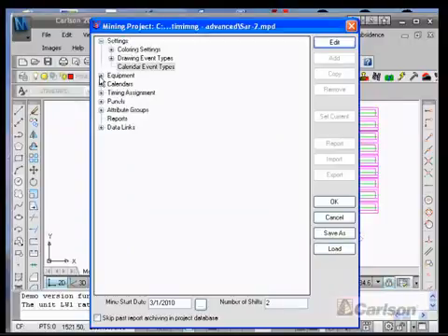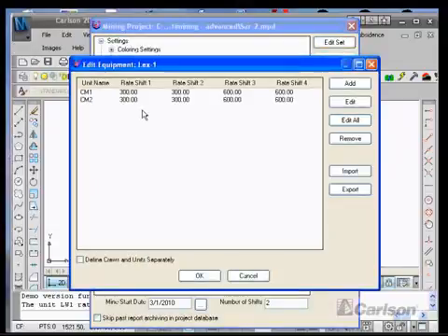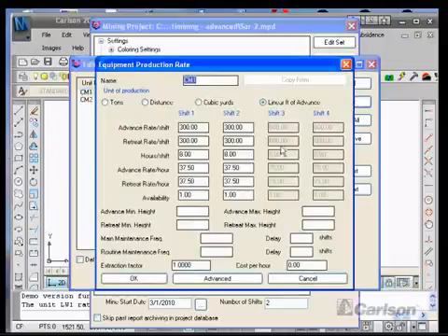When we define equipment, we can edit the set. The set name is Flex 1. And if I edit equipment, I can give it a name. We can schedule the equipment in tons, and if your drawing's metric, that'll be metric tons. Distance is typically used for a longwall.